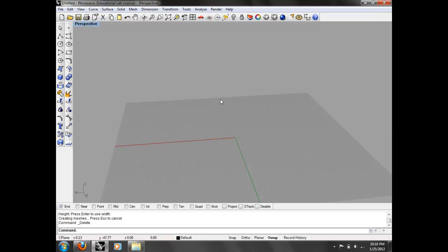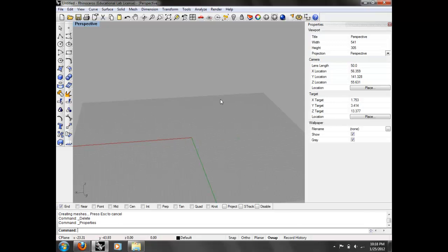To access the properties panel, you press F3, and it pops up. Okay, it occupies a space. So you can see here it says this is actually giving us information about our view, because I don't have anything selected, so it's talking about the view. This is a perspective view. It gives us the camera lens length, where the camera is. This is really critical stuff. This is what we're going to use.